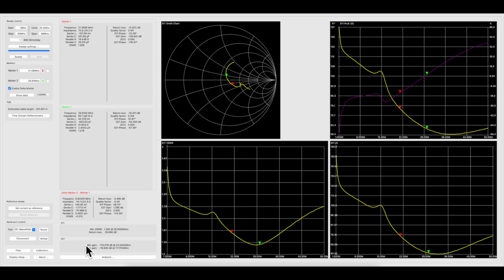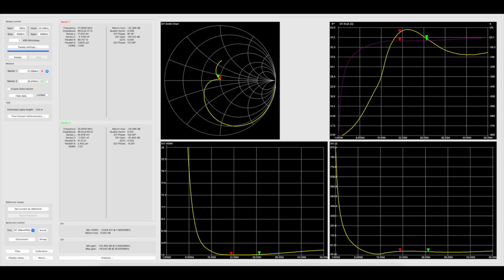The difference that it makes, so if you look at this here on the SWR chart, now check this out. Look at that. And you can see instantly, look, this is the bullseye point, and these two are now very close together, very close to the central 50 ohms marker. And look how flat this is. Now you can see clearly why it's a high pass filter, because look, the SWR skyrockets below about 15 megahertz, but is amazingly flat right through really to 50 megahertz and beyond. But over the bit that I'm interested in, superb.